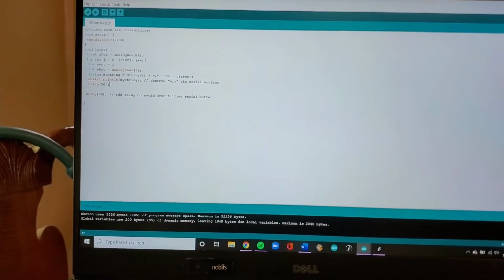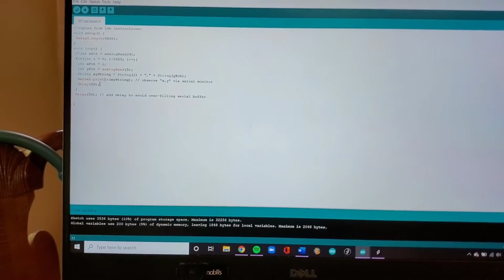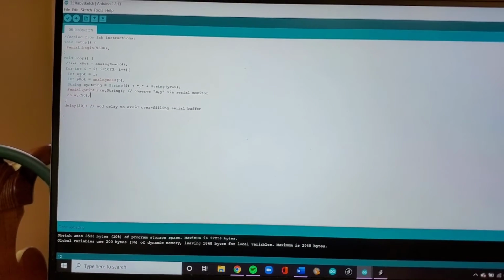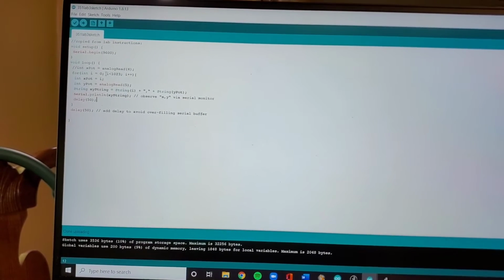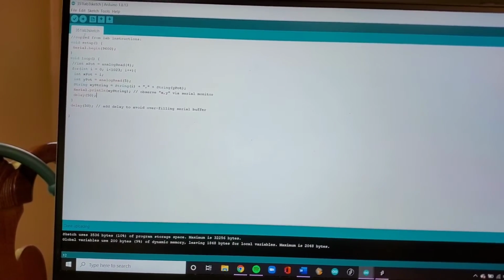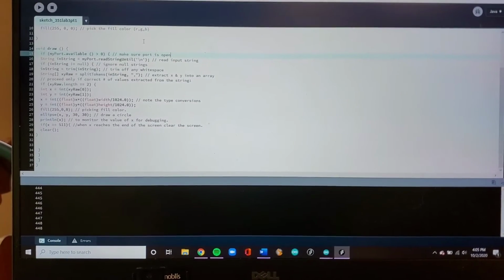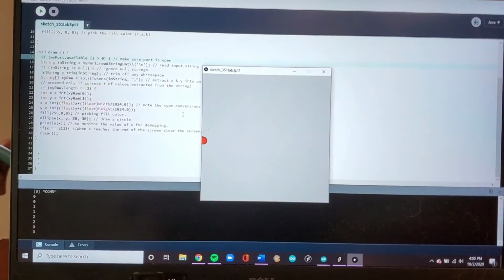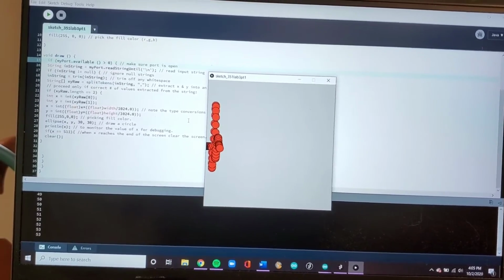So to get an ellipse moving from the left to the right of the screen in increments of 50 milliseconds, I went over to the Arduino window and set my x value into a for loop, where it would go from 0 to 1023, incrementing by 1 every 50 milliseconds. And then once we give that an upload, we see that it will run. I can still control the y, but the x is progressing.